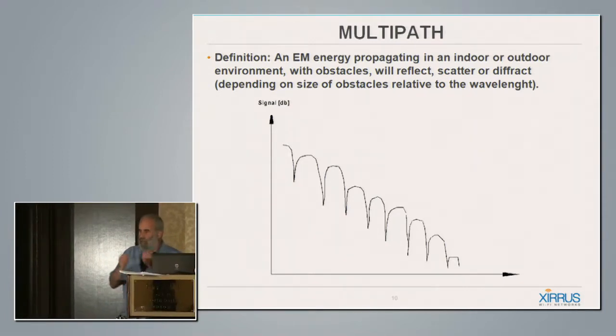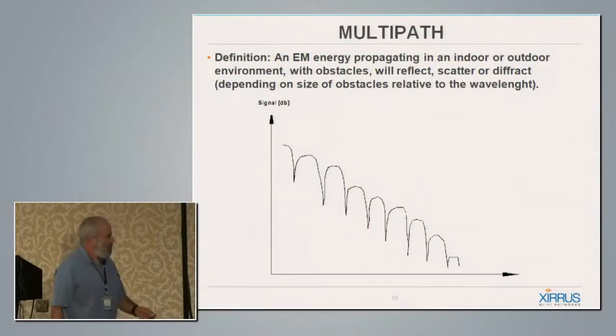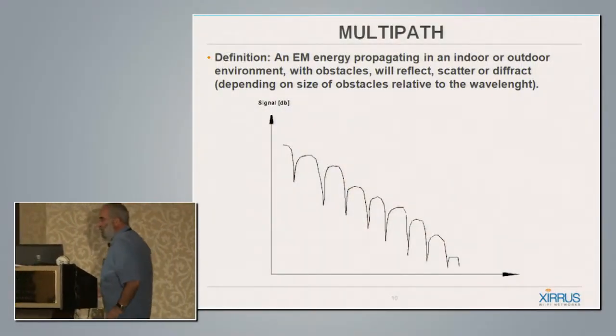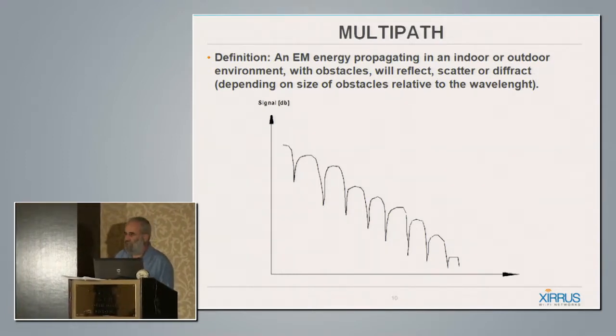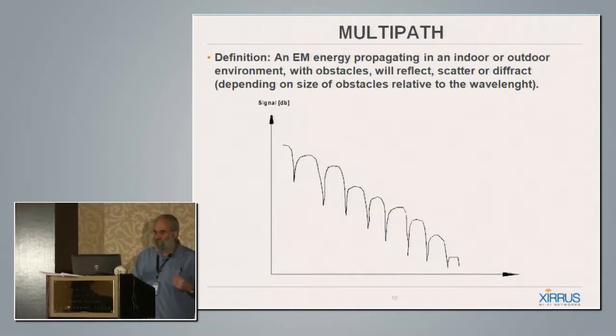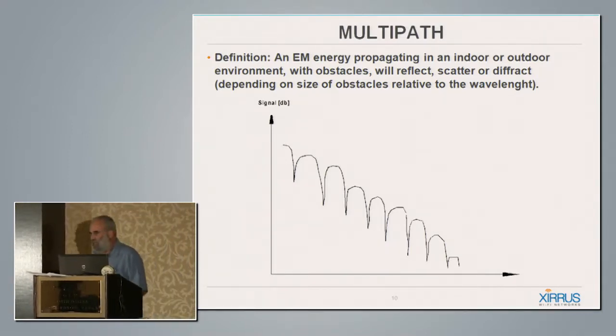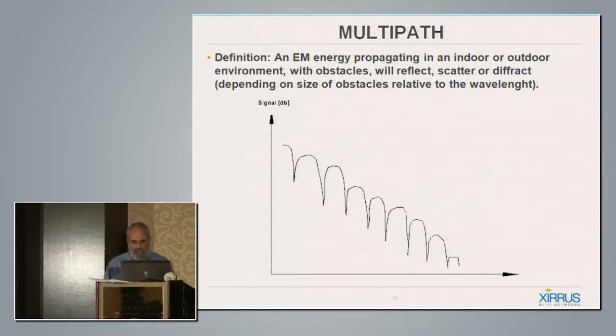Those dropouts may become most significant when we are at very low levels, when the signal is very weak, and any small reflection might be canceling it. So sometimes you stand in a place, you move a couple inches back and forth, and the signal can change 10 dB and more quite easily. And so when you design products, obviously, when you design access points with the antennas, you try to think about all those issues up front.